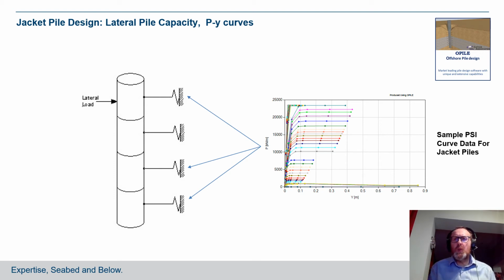As mentioned, we also do need to look at lateral pile capacity, and this is information that's passed on to the structural designer to input into the structural models. Part of that is PY curves, horizontal loads to deflection curves for the piles, standard codified ways of working out this information, and we use an in-house software called Allpile to do that.